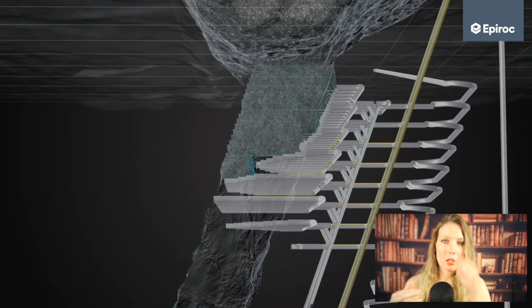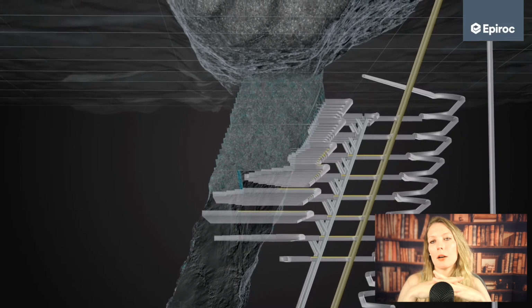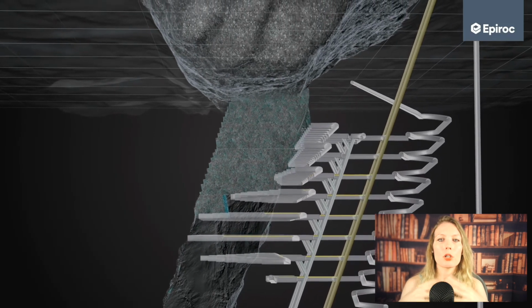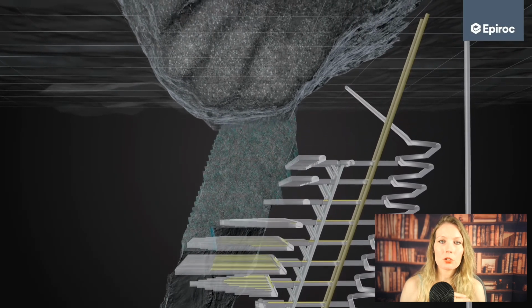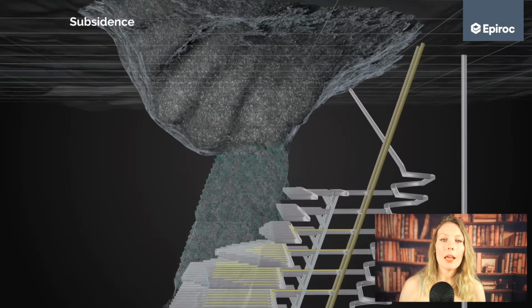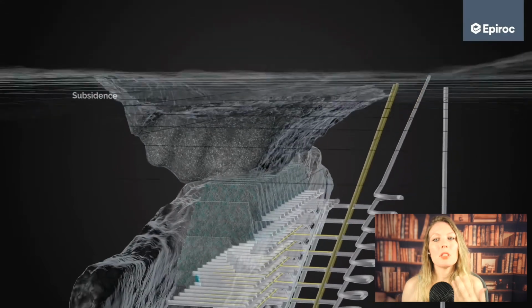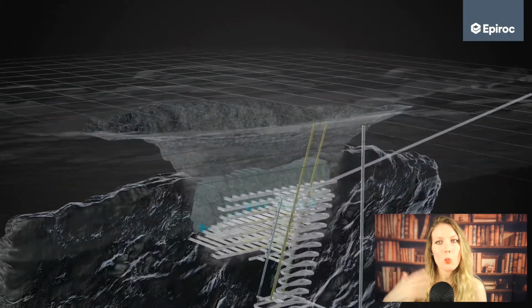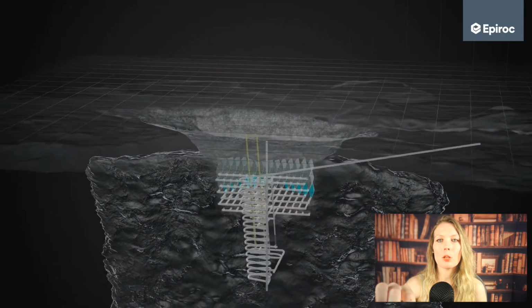For example, in weak rock conditions, larger stope spans may require additional ground support, such as cable bolting or shotcrete application. If these geotechnical constraints are not factored into the stope optimization process, extraction could become unsafe and require expensive remediation efforts. Conversely, in highly competent rock masses, wider stopes may be feasible without additional support, reducing cost and improving efficiency.